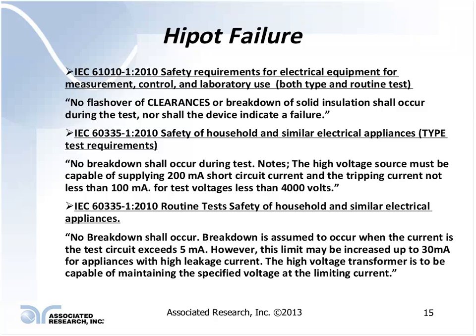So whenever we're testing the insulation within the product, no flashover is allowed, no breakdown of solid insulation is to occur during the test. That is the failure condition that we're looking for, making sure that does not happen.